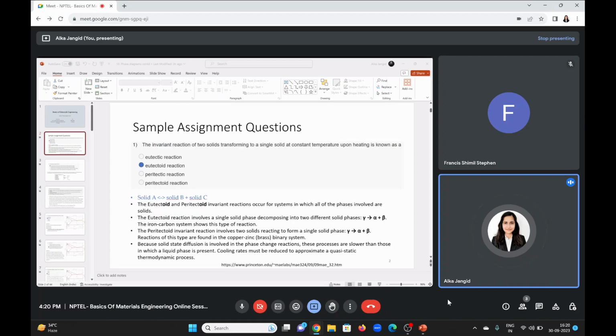In metallurgy, you mainly study wrought iron when you contrast wrought iron versus cast iron. Cast iron is made by casting your iron, and there'll be a lot of impurities, so it acts as a very brittle material. But when you talk about wrought iron, you'll have a very low percentage of carbon, so it is ductile compared to cast iron. That is the only part I'm aware of. I'm not aware of how the processing works, or why they are adding slag.